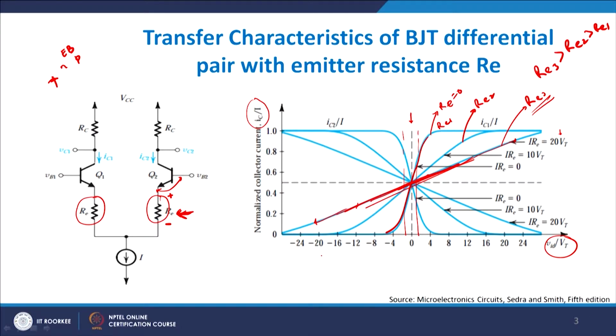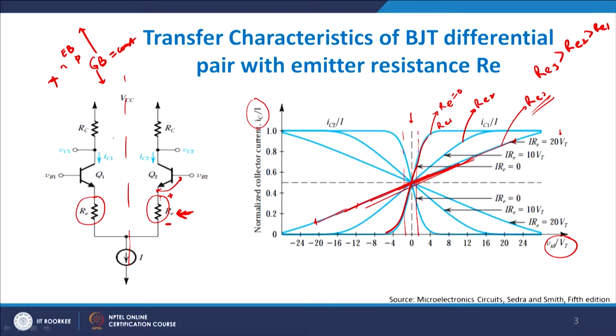Why does it increase the linear region? Because if you remember, the gain bandwidth product is always constant. So, when the gain falls down, you can work with a larger bandwidth, your bandwidth increases, and therefore your linear region of operation becomes larger and larger in this case, right. So, that is the reason we can use this. Please understand, all these discussions are with the tacit assumption that both the arms here, left arm and right arm, are exactly symmetrical in nature. If they are not, then this does not hold good, there will be some changes which you need to make.